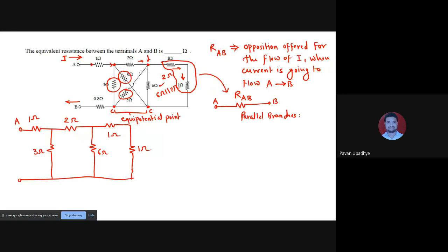Now we will redraw these branches. Now as I said, this 3 ohm, look at this carefully, instead of showing it connected between D and C like this, so let us name D and C over here as well. So see, what you need to do is you have to draw a 3 ohm resistance between D and C. So what they have done is they have drawn it diagonally in this rectangle. Instead of drawing it diagonally, what I prefer is I would draw it in this manner, because we know that these two are the same points.